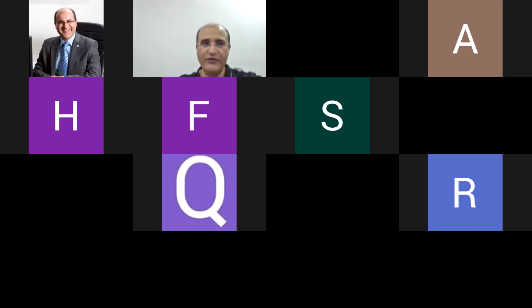I'm gonna stop recording. If you have any questions, you can stay. But I'm done. This is basics of serial communication. You can think of any idea how to implement any program. By the way, in the slides, I really used to do this with the students in class. We wrote code to read the analog to digital converter, read the value, convert the voltage, send it to MATLAB Simulink, draw a graph of the voltage, how it's changing with time.